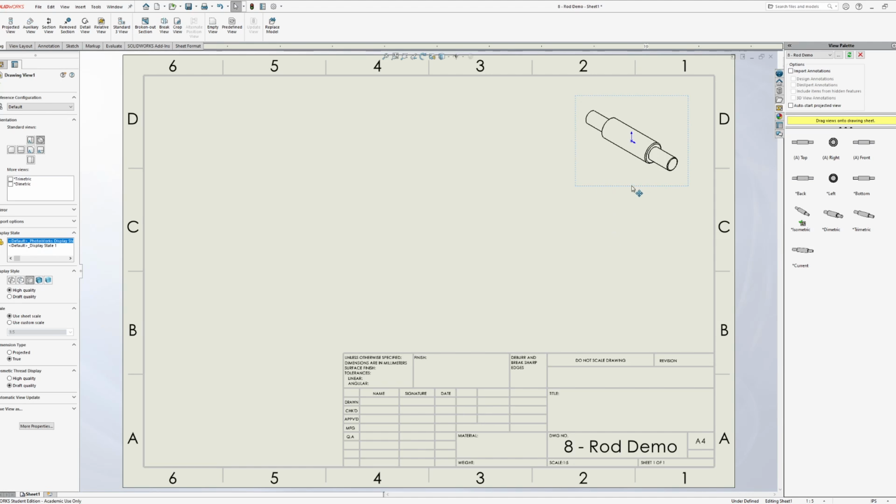I tend to like this one just because I'm able to immediately drag and drop parts into my interface. So what I generally like to do right off the bat is put my isometric view in there, just because it'll give me a good semblance of what kind of part I'm working with here. And for these isometrics, I also like to choose the second from the right option, shade with edges, because it gives a very good idea of what we're looking at.